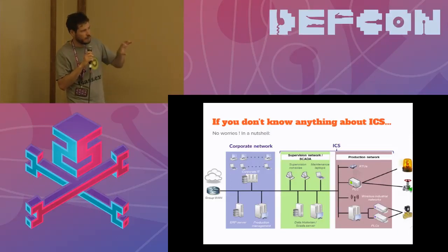Those physical devices are managed by PLCs. That's the device we're going to talk about today. That stands for Programmable Logic Controllers. And mostly it's an embedded computer with electrical inputs and outputs. That's the main difference between a standard computer and a PLC. Those PLCs are then managed by some classical IT stuff like Windows servers and workstations running what we will call today a SCADA software. I'm not digging into the detail of SCADA versus DCS and stuff like that. Today we're going to call that SCADA. And somehow this is connected to the corporate network to get some information or send some batch orders.